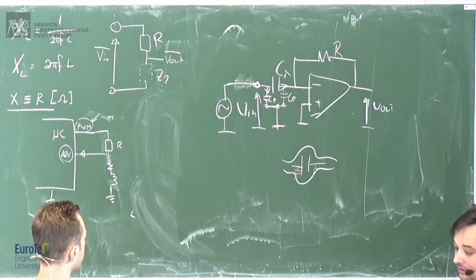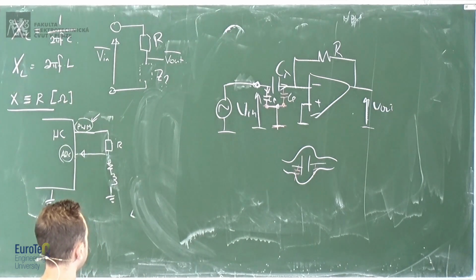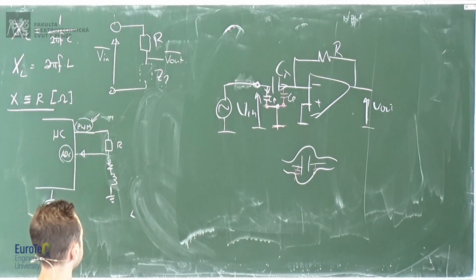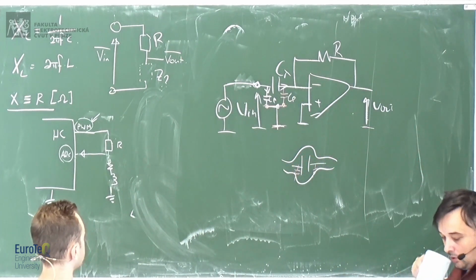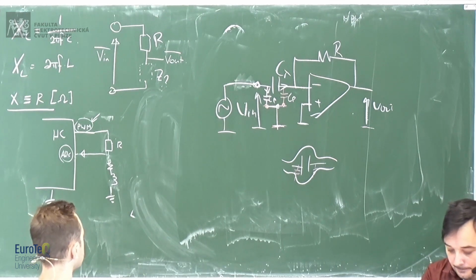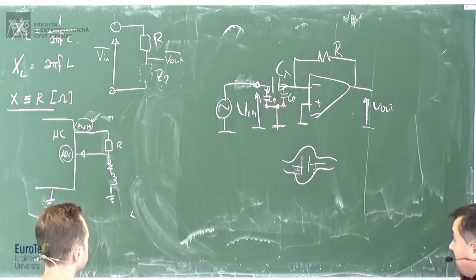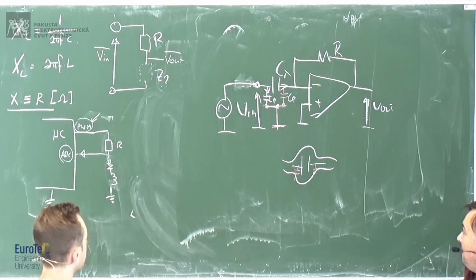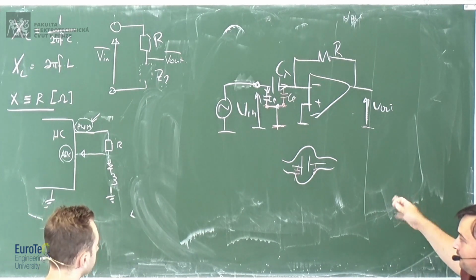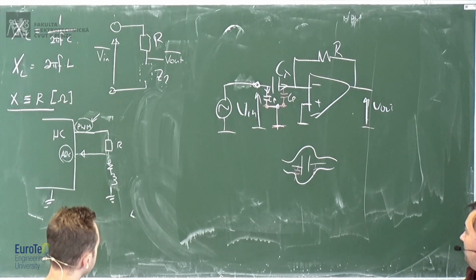Like, what source of uncertainty do you see here? The components themselves, and the op-amp, and the device you'll be measuring the V out with. Well, the op-amp, yes. Then what? The uncertainties of the components. So, well, actually, C is unknown, but R will have some uncertainty in it. Possibly the voltage generator could also have some uncertainty. The voltage, of course, has some uncertainty. You think that it's 1 volt, but is it really 1 volt? 0.99. Then it depends if you have the modulator, you have the noise of the demodulator. If you do it digitally, you will have other sources of uncertainty and all these sorts of things, okay?